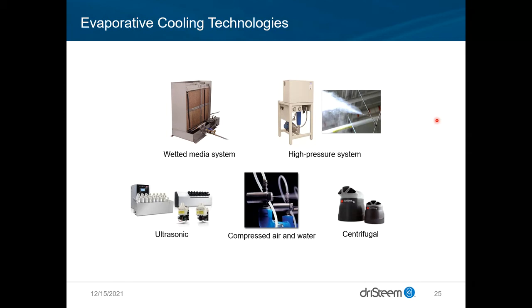So these are optimally used when you have additional heat in the space via process or the climate. Obviously, in the Southwest of the United States it's very common to see these just because of the climate. So keep that in mind when you're choosing systems. The other nice thing is, especially with these bigger high pressure systems, they are at pressure. So now you're talking about supplying potentially multiple zones with a single generator. So in very large buildings, with high loads and many air handlers or zones, they become very cost effective.